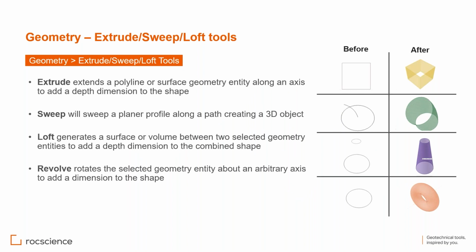As I mentioned, when you have lines, you can make them surfaces or volumes. You have to know that if you have a 3D model and you want to do a 3D analysis, the software packages only work on volumes. Surfaces come in for things like groundwater analysis, such as a water table, an anisotropic surface, or weak layers.